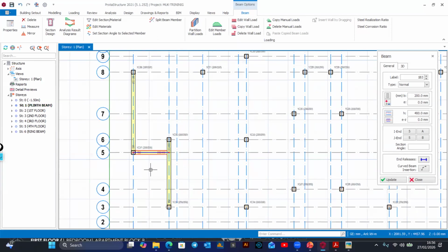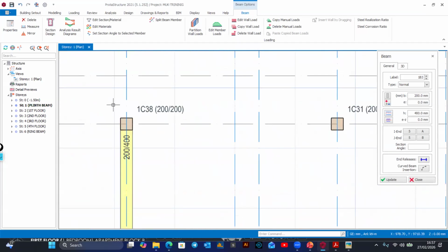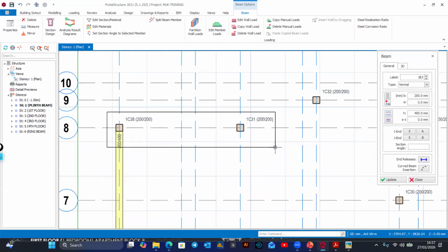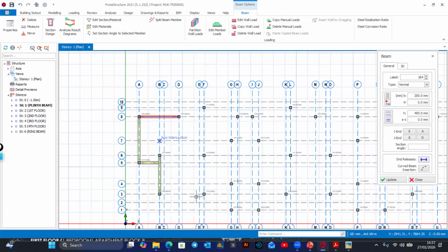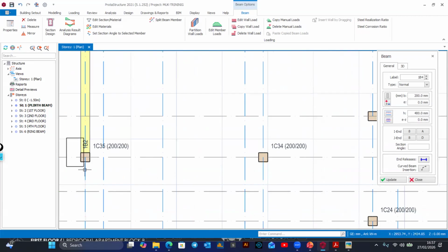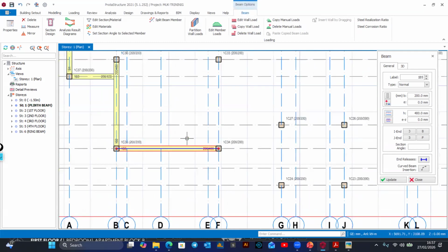So my point here is when you're drawing beams, they should be at axis intersections where you have supports. But then it will take a lot of time for you to identify axis intersections. You can also just make a window selection like from this point. As long as you have enclosed the supports very well up to there, you click. Like I can draw from this point. Don't drag, just click that point, enclose the two supports, and then click that point.